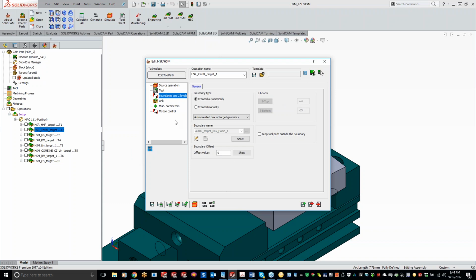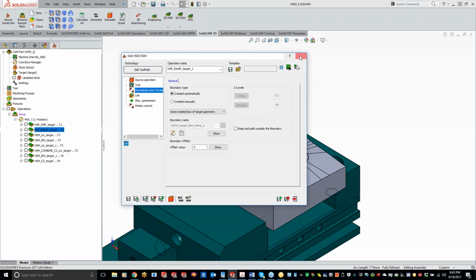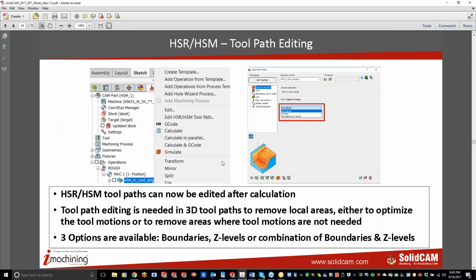Nice thing you can do with that too is, let's say you are running toe clamps and you want to avoid those toe clamps. We had that option before, but we could only specify a distance, and we didn't have a good visualization. So now what you can do is do a simple sketch on there and just tell it, do not touch this area, and it will keep it away for you. So I'll show you an example here.